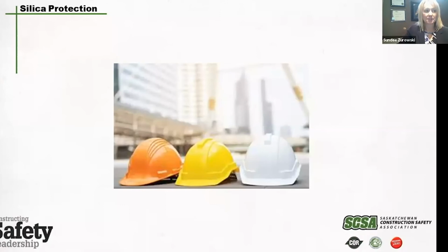Employers and employees should consider substituting, if at all possible, a safer material, and changing work practices to reduce exposures. Administrative controls: install signage warning workers of the hazards and informing them about the required protective equipment needed in the areas where they may be exposed to silica. Using work practices to reduce exposure is often less expensive than other control measures. However, workers must be trained to use practices properly and have their work activities monitored by the employer.